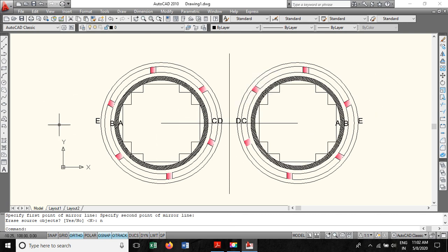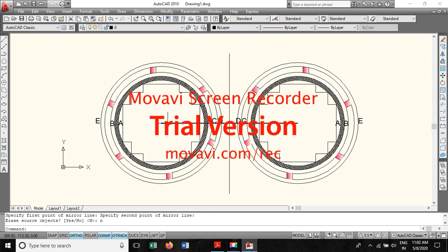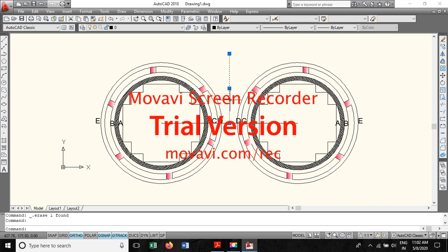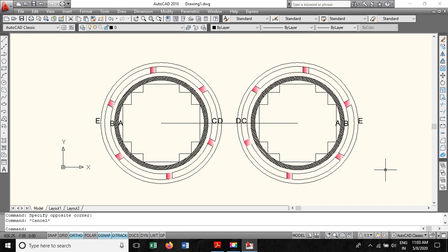So this is the sectional plan of the transformer. As I told you, once the core center distance is given as 350 mm, you have to choose the outer LV diameter carefully so that these two circles will not coincide. So this completes the sectional plan of the core type transformer.